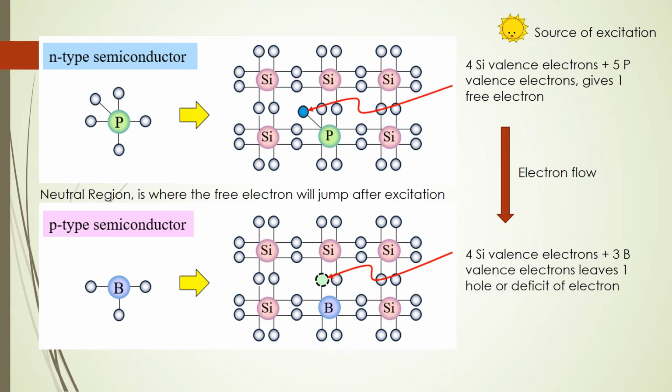An N-type semiconductor is created when the dopant is an element that has 5 electrons in its valence layer. Phosphorus is commonly used for this purpose. The phosphorus atoms join right in the crystal structure of the silicon, each one bonding with 4 adjacent silicon atoms just like a silicon atom would. Because the phosphorus atom has 5 electrons in its valence shell, but only 4 of them are bonded to adjacent atoms, the 5th valence electron is left hanging out with nothing to bond to.